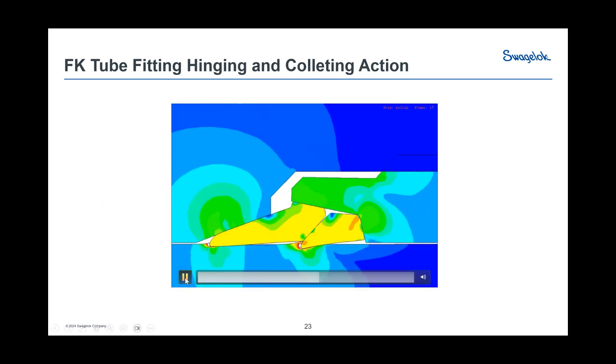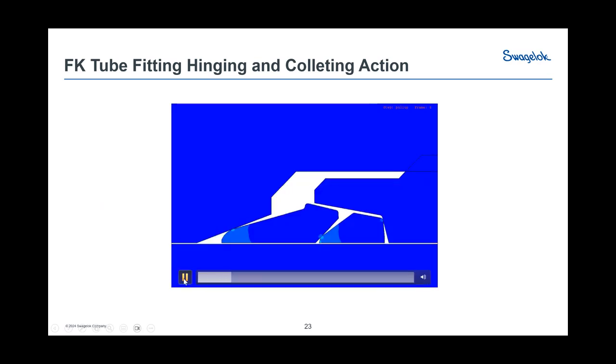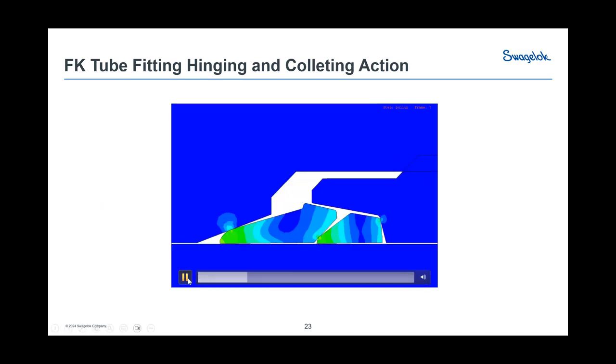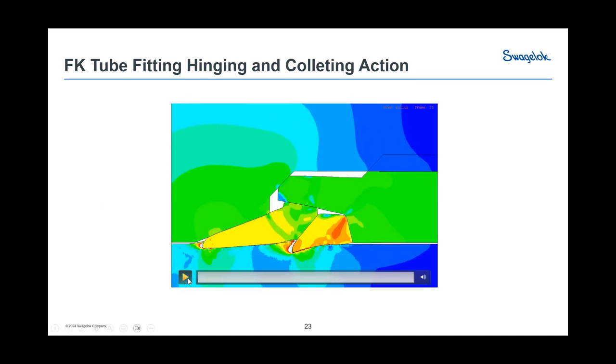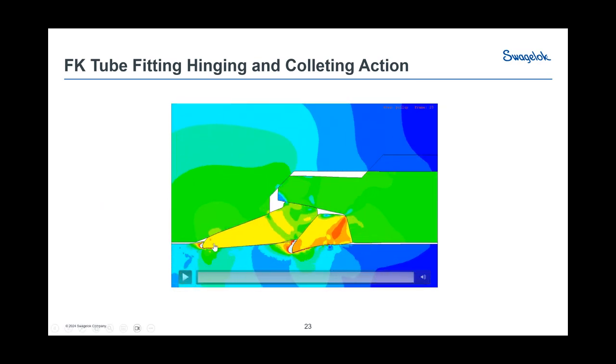But as you watch this, it moves kind of quick. You'll see with the back ferrule driving under the front ferrule driving forward. I'll play it multiple times. What you see there is stresses coming in different colors. Think of them like weather radar. So the darker the color, the more stresses that are being built up. You'll see the back ferrule drive under the front, lifts up the front ferrule, and it slides along the body, and then it slides along the tube.